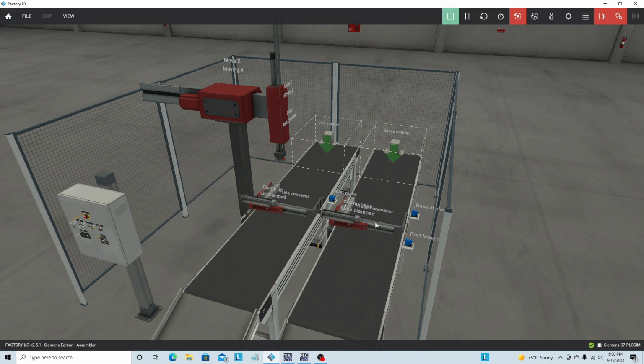If the command is 1, we're going to find our position or home it up. If the command is 2, we're going to go to home position in manual mode, which would be released. If it was 3, we're going to go to our clamp position or our work position in manual mode, and then 4 and 5 for automatic modes.